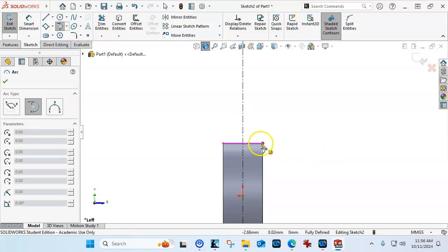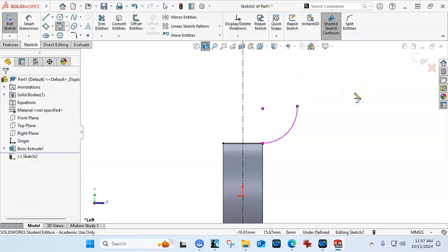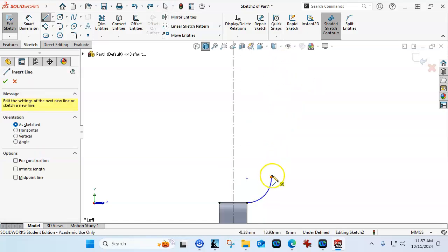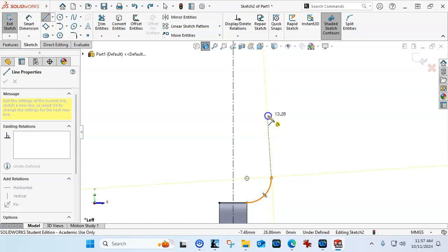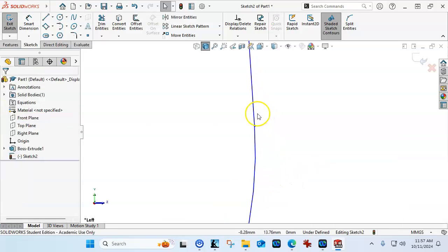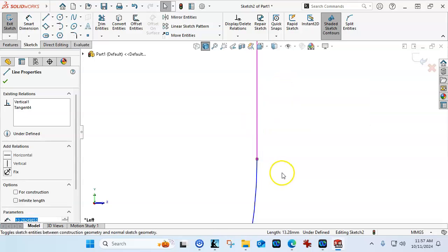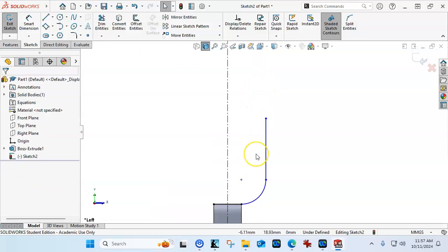And then we're going to bring off a tangent arc and go not to another tangent arc, so Control Z. And since I'm out of that, I'm just going to hit L on the keyboard to jump back into the line command. And looks like I missed something there. It is pulling tangency, so I would like to see if it, yeah, all right. I got my geometry, so I'm going to apply the vertical. And then our overall height is 47, so let's get that in there.